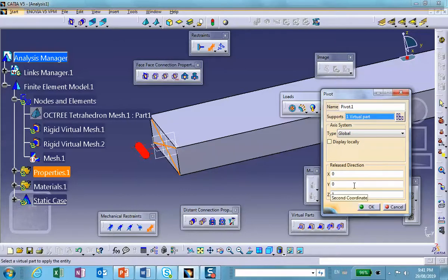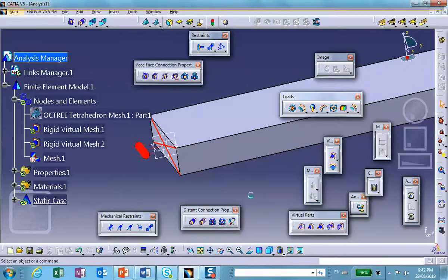In other words, this can pivot or hinge about that axis, but it cannot go up and down. It cannot translate at all. You know, the translation is restrained. Okay. Now you can also have an arbitrary orientation, for example, something like that, which obviously that's not what we want. Okay. So let's start with axis along x, which is right there.